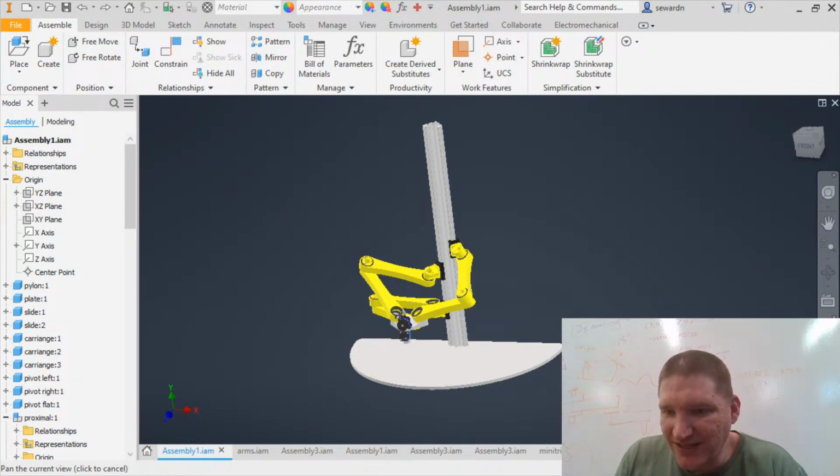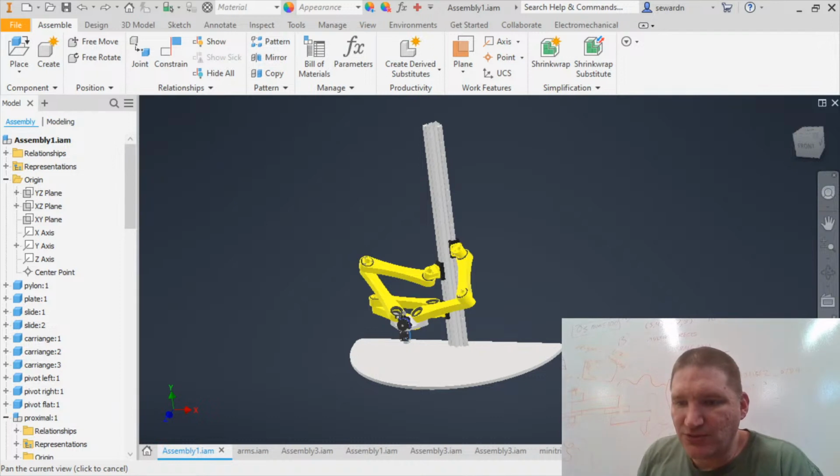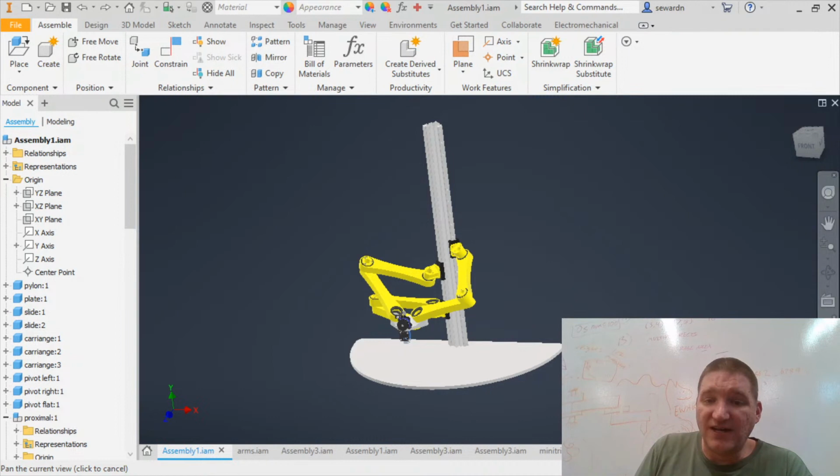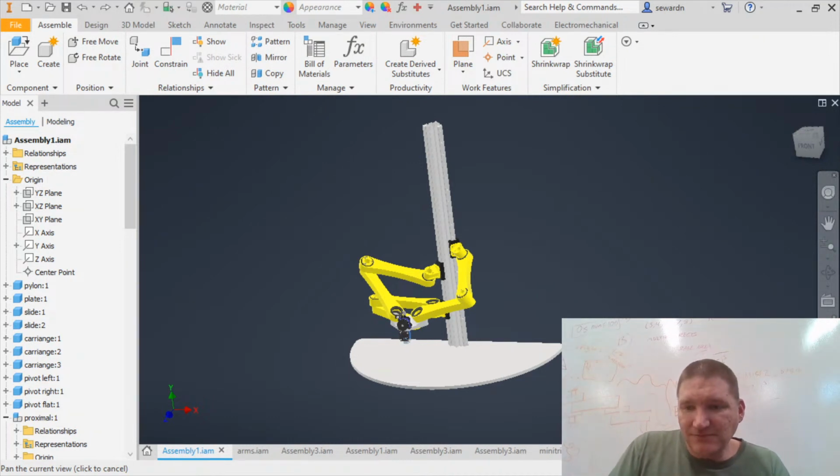All right, everything working. Sounds good. Okay, it seems like TMC enables you to drop the end stops. They feel the stepper stall. Not sure if they're accurate enough for bed probing too. So yes, TMC or Trinamic drivers can tell me if I stall, so I will not have any end stops. I'm anti end stops. If you can get rid of a part, no part's the best part. Since the resolution's the same everywhere, I will start early on by just putting the effector on the bed and saying go.